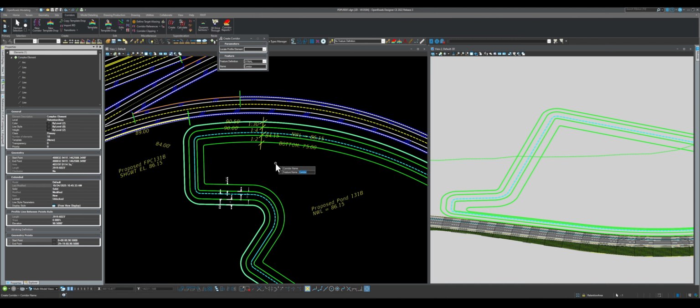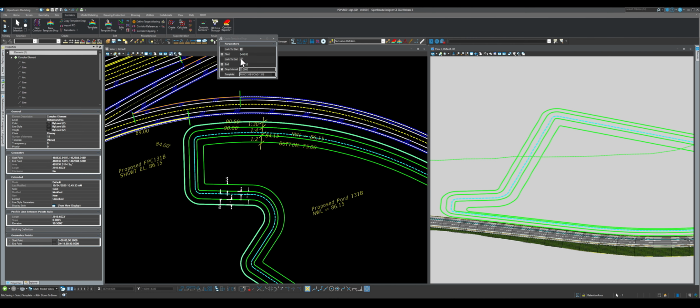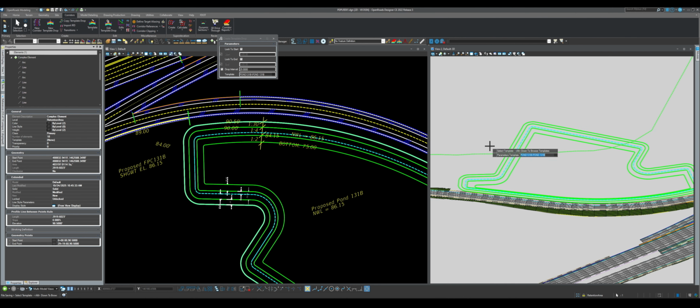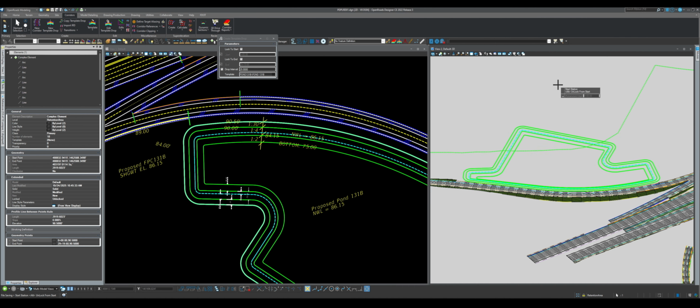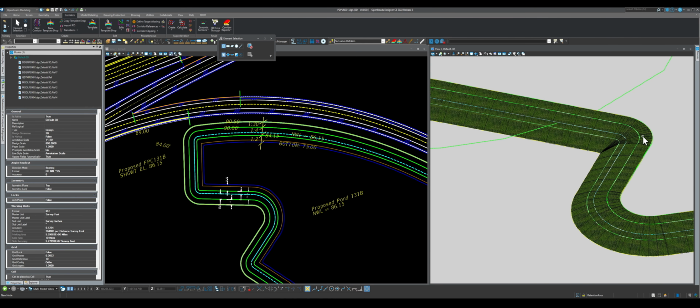And then reset for active profile, and then the corridor is going to be called pond 131B. Then let's select the template, which is this one, and I want it to start from the start and lock to the end, so you can go all over it. Let's see it make it right now. So click, click, click, and fingers crossed. Ta-da! Here we go, it made it.